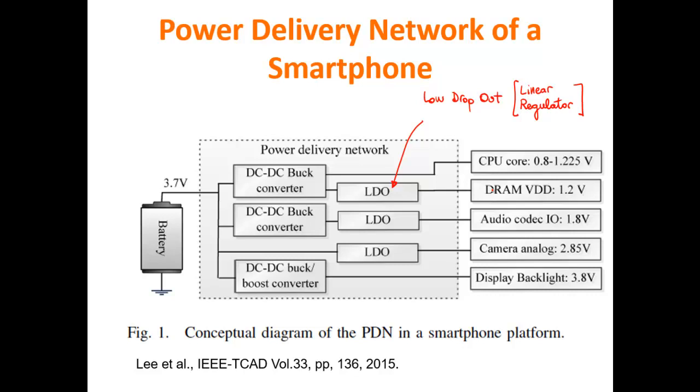So when you need a very constant and regulated voltage, you need to provide an additional block, which is typically called an LDO. For those of you that have followed the basic electronics course in the bachelor's, in the laurea triennale, you have called it a linear regulator.